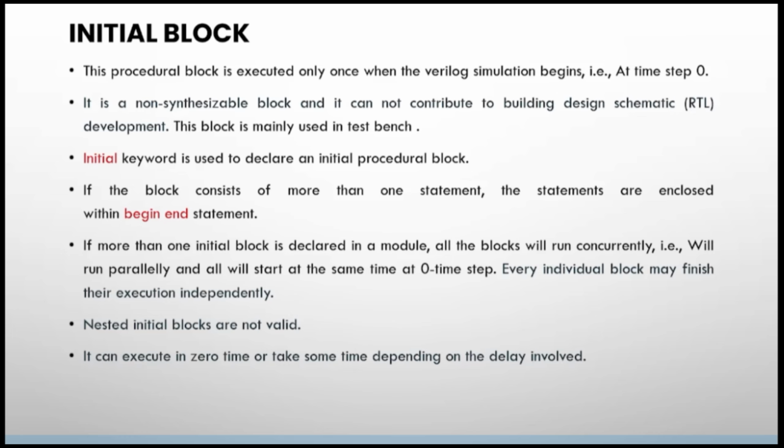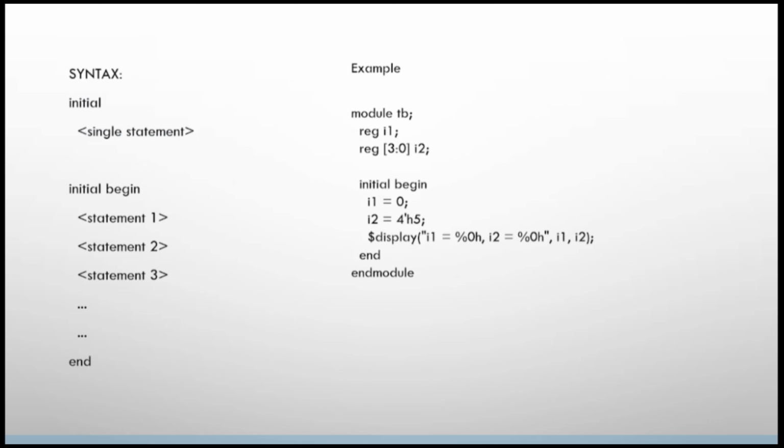Also, one thing you should avoid while you are writing this initial block is nested initial blocks. That means you shouldn't use one initial block within another initial block. This should be avoided. Also, you can use delays in the initial block. So this is about the basic idea of what an initial block is.